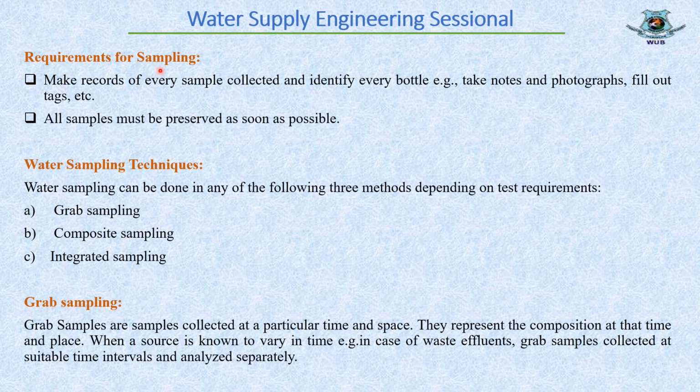Requirements for water sampling. Make records of every sample collected and identify every bottle. For example, take notes and photographs, fill out tags, etc. All samples must be preserved as soon as possible to get accurate results. Water sampling techniques. There are 3 techniques for water sampling, and they are grab sampling, composite sampling, and integrated sampling.